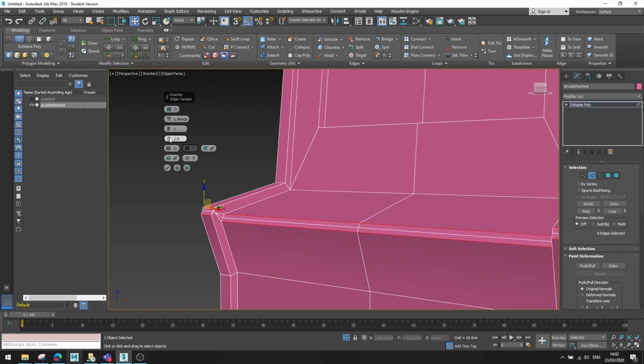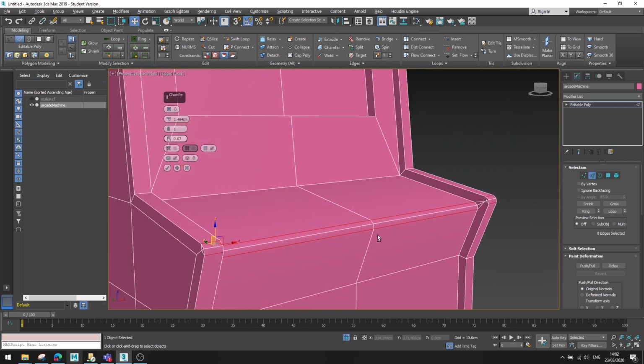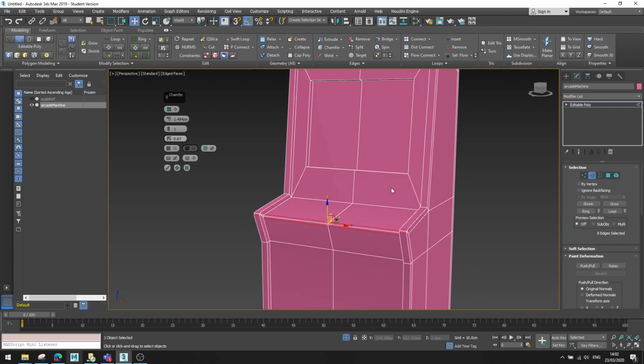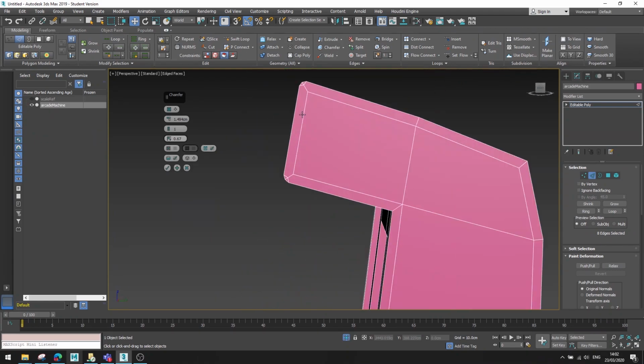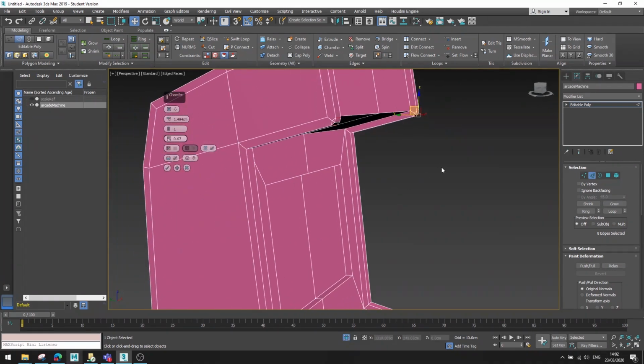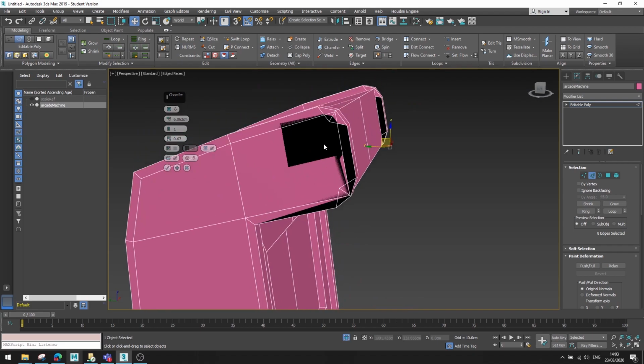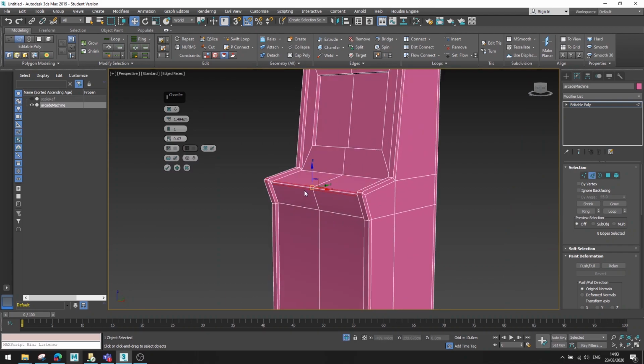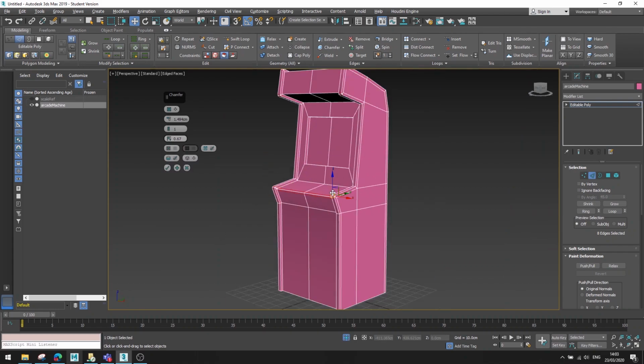So you might want to have slightly rounded chamfers, which will give you a nice look like that. You can change the tension, you can change the size of the chamfer, but be careful you don't push it too much, otherwise you'll get intersecting and overlapping geometry. So just be a little bit careful with how you apply it, not too much, just enough to get that rounded shape.